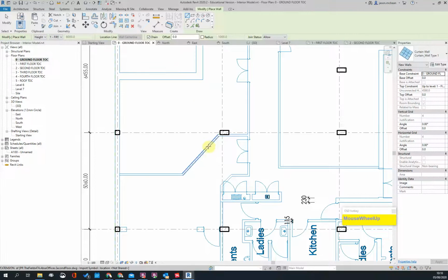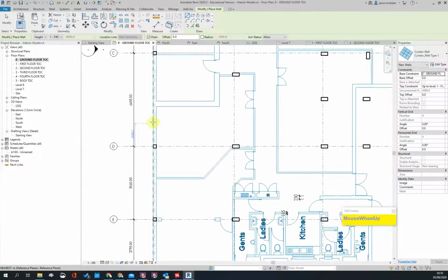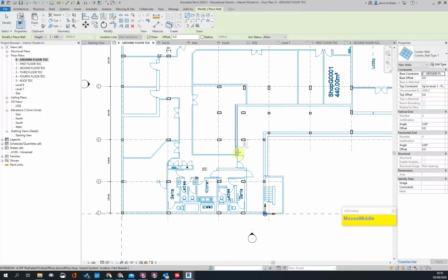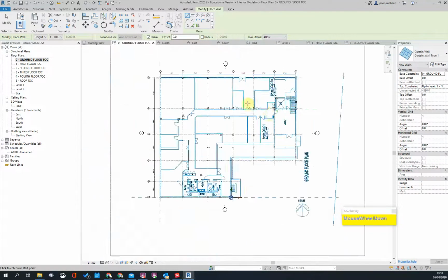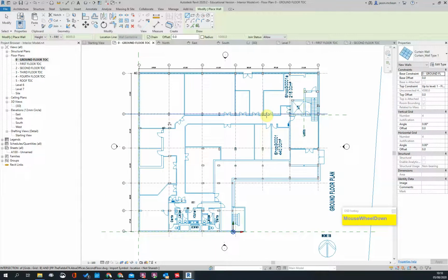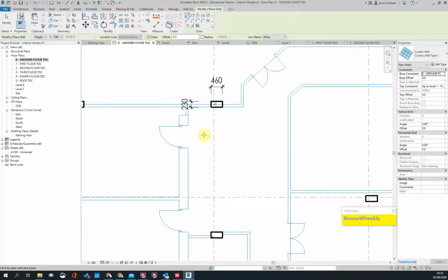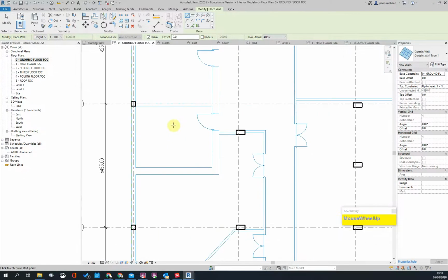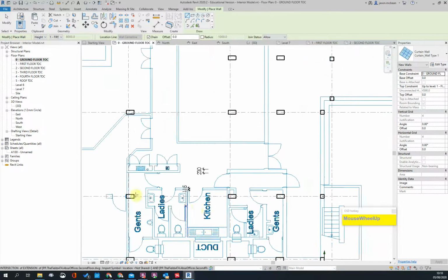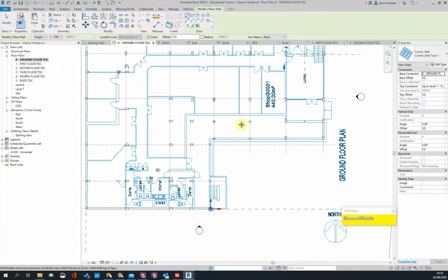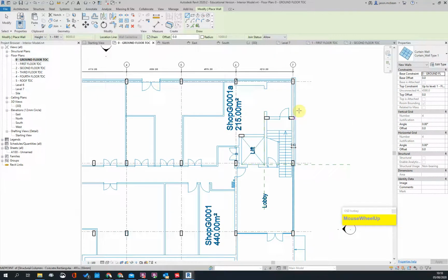I've got a stud wall, which I might have to create here as well. For this model, I'm not going to create the internal stud walls, because generally, in these types of projects, that stuff gets cleared out and demolished in any case. But I might establish some of them just for the sake of modeling. I'm more focused on establishing the external walls, the bathroom walls, the stairs, and that kind of thing.